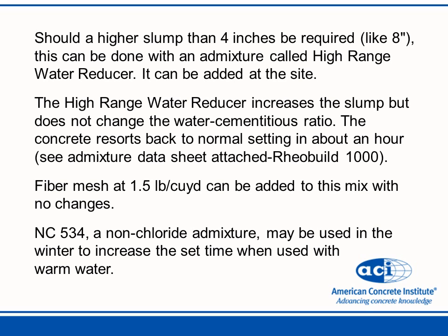And this was some of the information that we put in the back of the submittal about the admixtures, and if fiber mesh was used, or a fiber, that 1.5 pound dosage could be added to the mix with no changes, and also that a non-chloride admixture could be used in the winter to increase the set time when used with warm water.